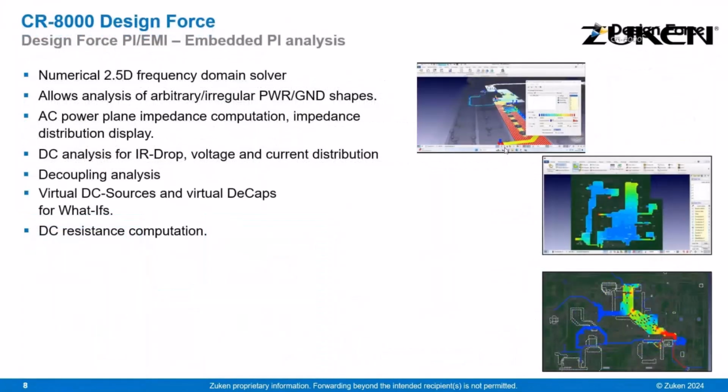DesignForce also includes powerful tools for power integrity and electromagnetic interference analysis. It uses a numerical 2.5D frequency domain solver that allows for the analysis of irregular or complex power and ground shapes. And this is especially useful nowadays for modern PCB designs where shapes are not always uniform.